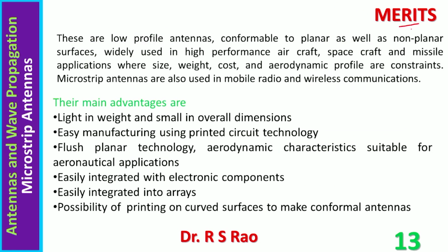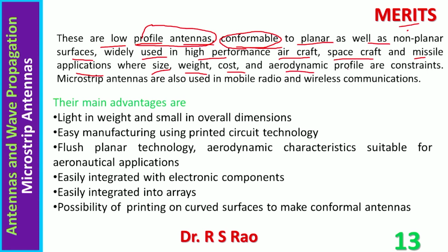Now we consider a few merits of these antennas. These are low profile antennas, conformable to planar as well as non-planar surfaces. So this is the biggest advantage: conformability and low profile. These are widely used in high performance aircraft, spacecraft, and missile applications where size, weight, cost, and aerodynamic profile are constraints. Microstrip antennas are also used in mobile radio and wireless communication.